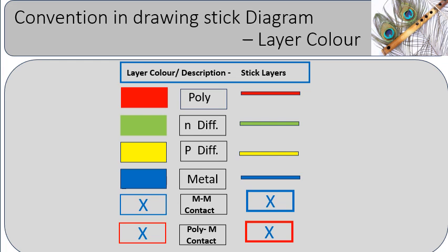In physical design, layout design refers to the geometrical representation of different layers of the chip. Each layer corresponds to a specific material used in chip fabrication. The layout layers are sorted out, masks are created and are used in layer processing. A typical processing layer color convention adopted in drawing the stick diagram is as mentioned below.